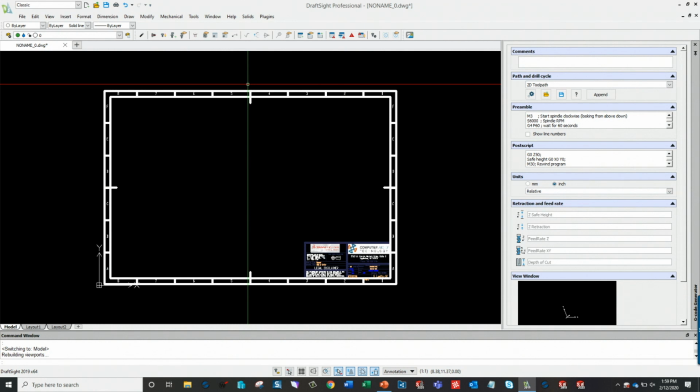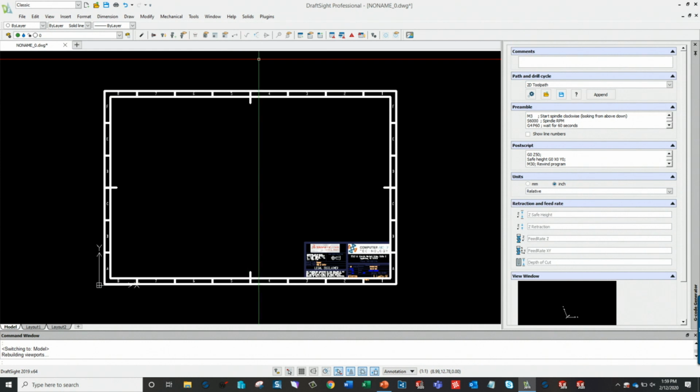We found in AutoCAD 2019 it's a very useful function nowadays, drawing comparing. So we use it a lot when we have the drawings and the frames in the model. They compare it, they give you one color for a version, another color for a different version, another color if everything matches the same. Correct. It helps us a lot instead of looking for one change during a version. Yep. That is in 2019.